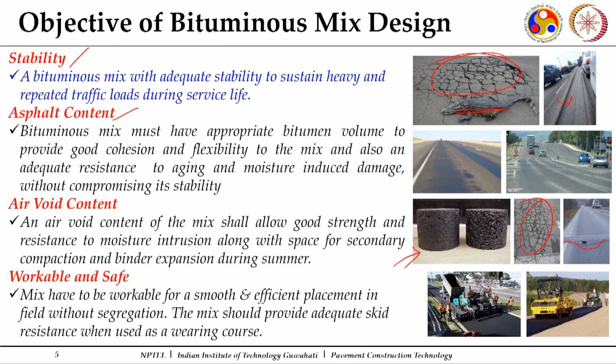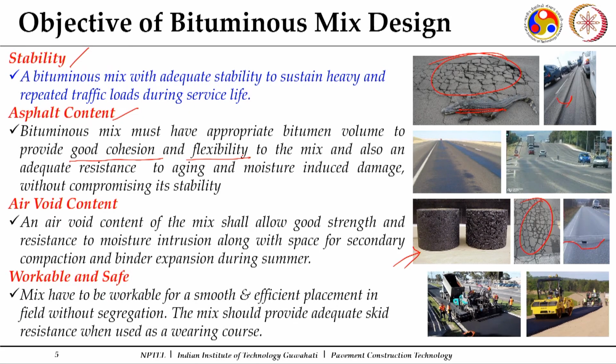Now, I need to work out a bituminous binder volume or quantity which is good enough to provide good cohesion, because the material has to have good cohesion. If good cohesion is there, then only it can take a good load. It should be flexible enough. If it is very stiff with a small amount of deflection, it will crack, because we have granular courses below, so there will be some amount of deflection. If the material is very stiff, it can crack.